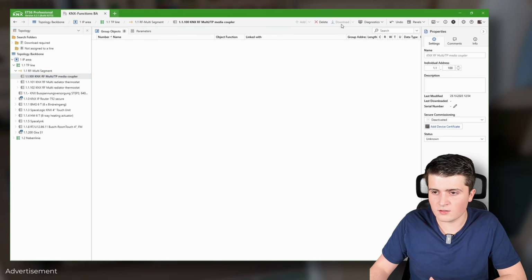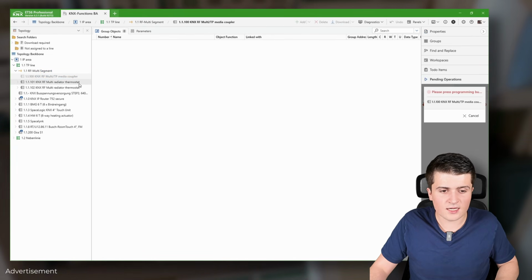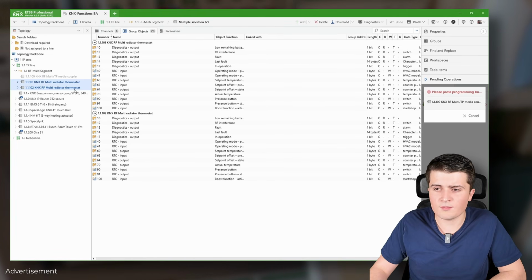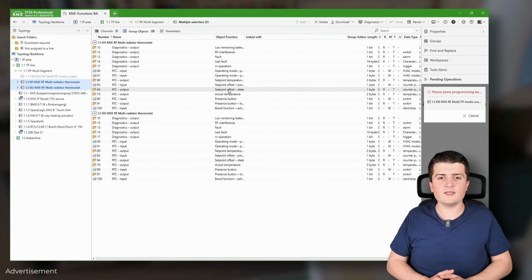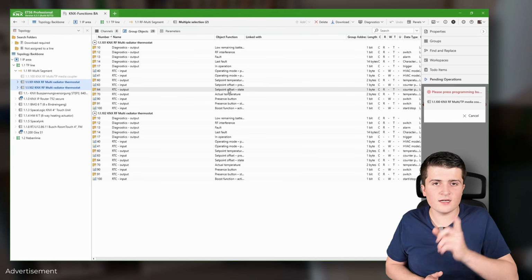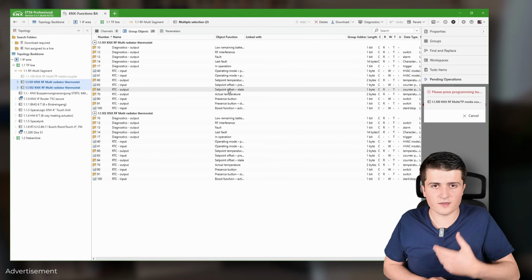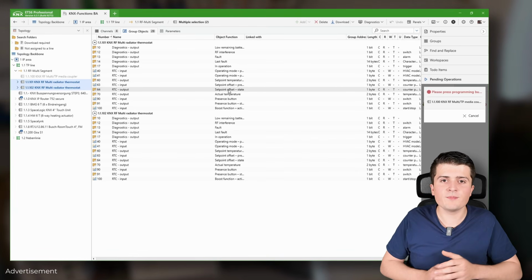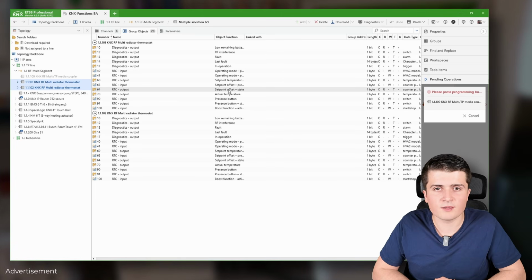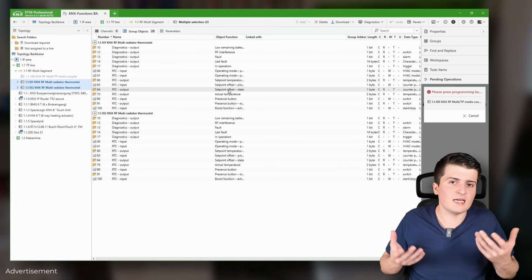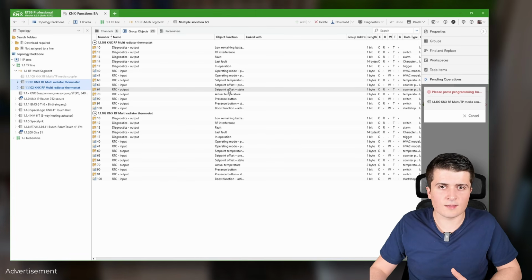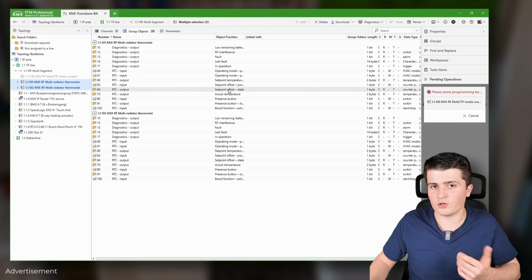So click here on download, and then I can start to download the thermostats, which I'll quickly do. So I'll simply press the programming button in my case. And what you should know is I mentioned that you can enter the device certificate so that you can download the devices via serial number. However, for battery powered devices, you normally also have to press the programming button so that you, let's say, wake up those battery powered devices. So that is something that you should consider or that you should know.